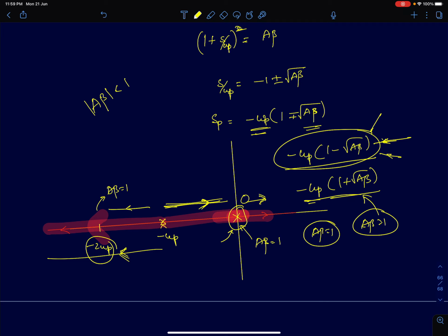So this is a simple way of understanding why in positively fed back systems we need to ensure that the loop gain is always less than 1. It's easier to visualize when you assume just 1 or 2 poles, then it's much easier to explain. So this is why, when we were analyzing feedback circuits, in a positively fed back circuit we impose this condition for it to be stable.